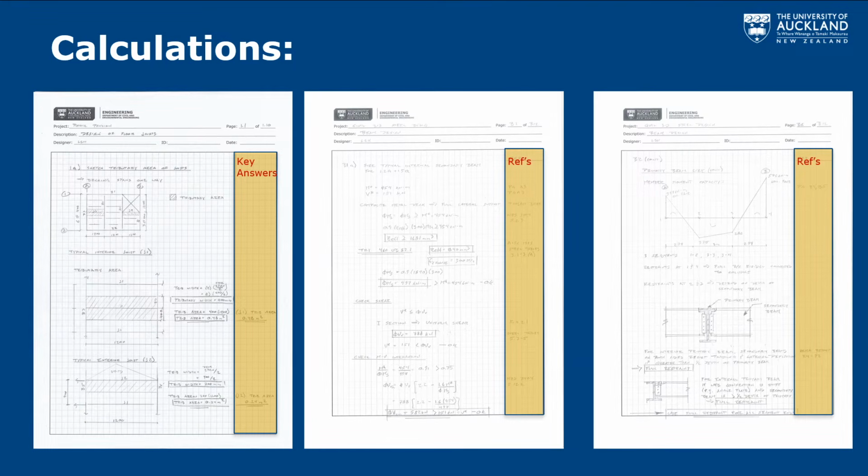And then just below that, you can see I've got a reference to NZS 3404. Similarly, all the way over to the right, I've got a reference of page B4 and B5 for what the moment demands are on this primary beam that is getting designed. And then I have this definition of restraint type, which is coming out of this Harrow report.